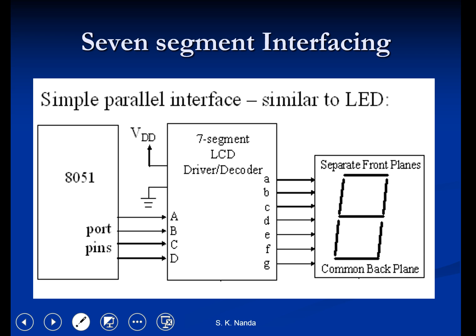It is based to count 0 to 9, it will work like a counter, which has 7 segment LED display interfaced to it in order to display the count. The simple circuit illustrates two things: how to set up simple 0 to 9 up counter using 8051, and more importantly, how to interface a 7 segment LED display to 8051 in order to display a particular result.